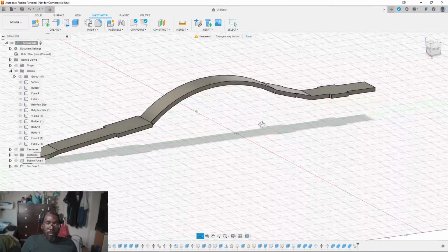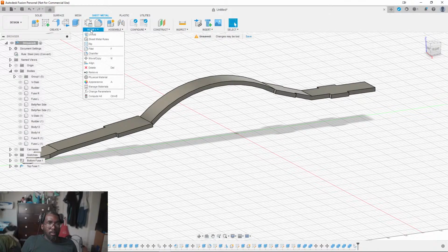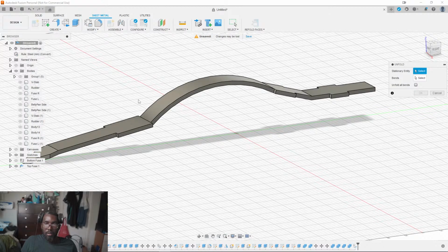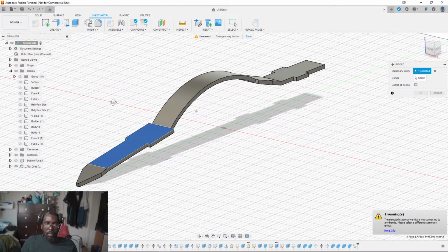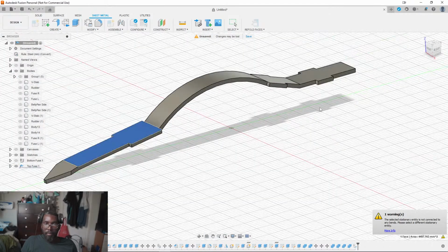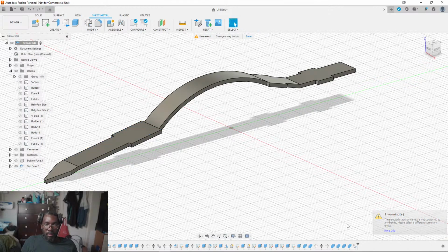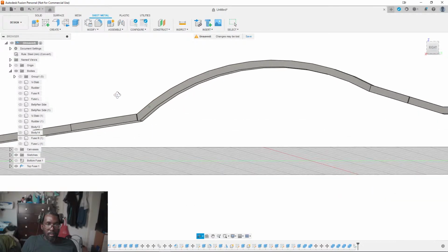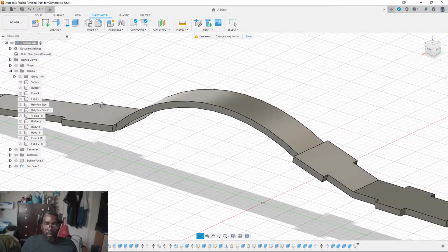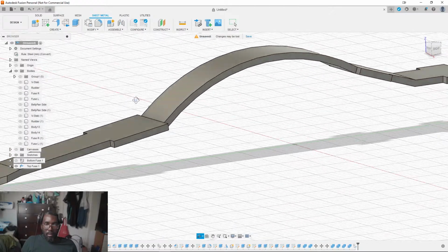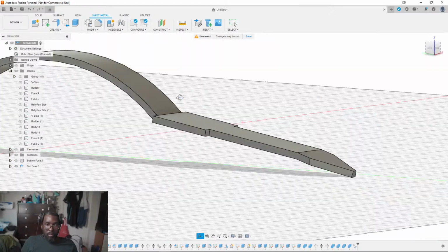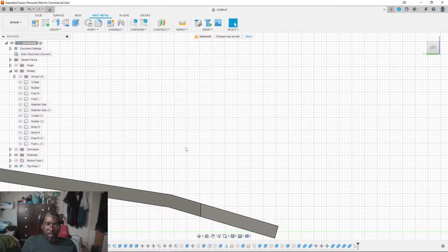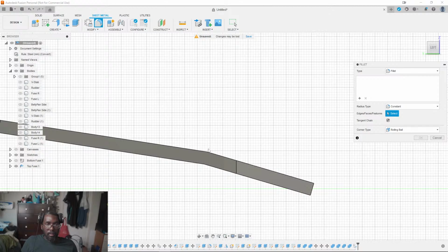Alright, I doubt any of the bends will work right now. So let's try anyway on full. Yep. So here's how we fix this. Everywhere that is supposed to bend, you put a fillet.